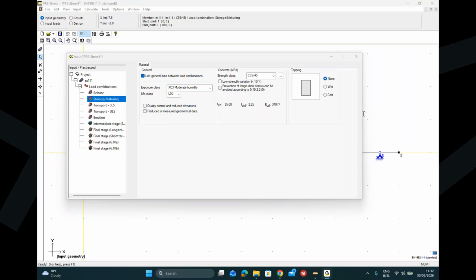So if I want to have multiple legs per stirrup, what I need to do is understand how many stirrups I have in that interval of distance between the load and the support. Even if my stirrup has 2 legs and I want, for example, to have 4 legs, I am just cutting the distance between stirrups in half, and you will get the same value, because mathematically it's the same number of legs intersected for that specific interval. I hope I was clear. If not, you can come back to me after, and I will explain it in a way that everybody can understand.